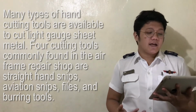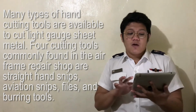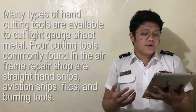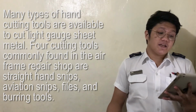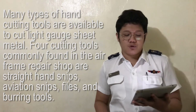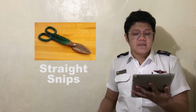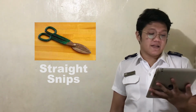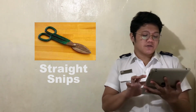Other tools for sheet metals are the hand cutting tools. Many types of hand cutting tools are available to cut large gauge sheet metal. Commonly found in the airframe repair shop are straight hand snips, aviation snips, files, and burring tools. First one is our straight snips. The straight snips or sheet metal shears have straight blades, with cutting edges sharpened to an 85-degree angle.